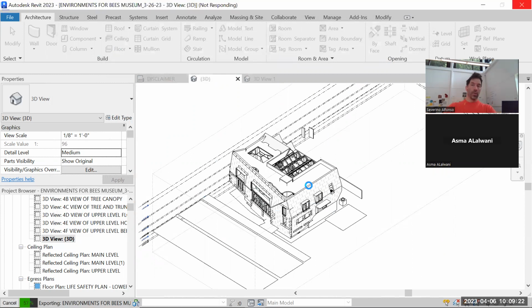So don't bring, you know, the cleaner it is, the better. You can clean in Rhino as well later on, but cleanest means don't bring things that you're not going to laser cut. I don't know, a furniture piece, or maybe you don't need columns at all, any other things that you don't need to laser cut. It's not worth bringing them, okay? So you will probably duplicate the view and just hide stuff. And again, you can hide things in Rhino as well later on.